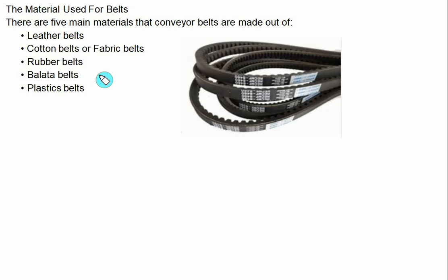Rubber belts are made of layers of fabric that are fastened with a rubber structure and have a thin layer of rubber on the face. These belts are very flexible but are quickly destroyed when allowed to come in contact with heat, oil or grease. One principal advantage of these belts is that they can be made endless easily. These belts are found suitable for sawmills and paper mills where they are exposed to moisture.